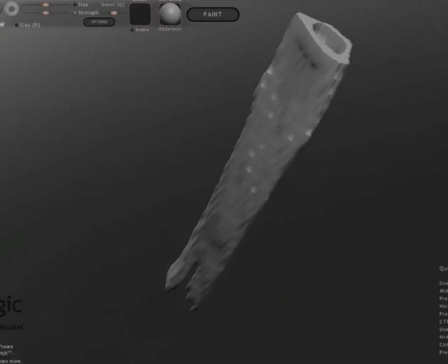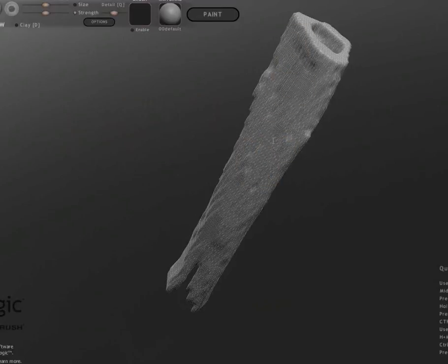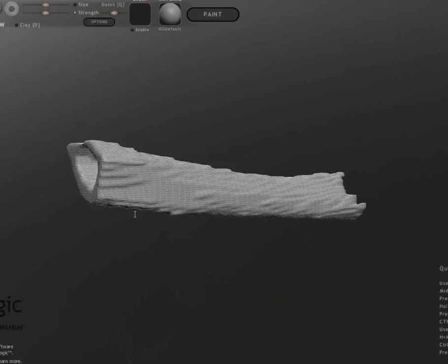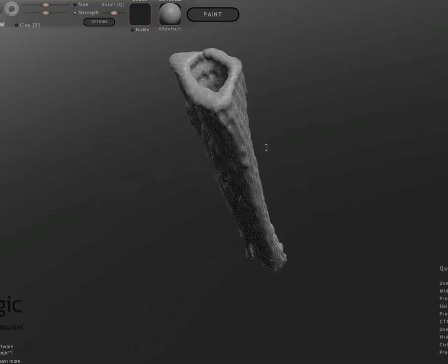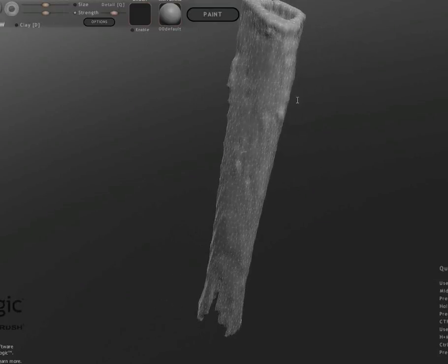But one of the first fascinating things you can do is greatly improve the structure of the triangles making up the object using the simple button called Reduce Selected. And I'm going to hit it a couple times, and you'll see what happens. You see what's happening? It's reducing the number of triangles, but it's maintaining the overall structure of the object.